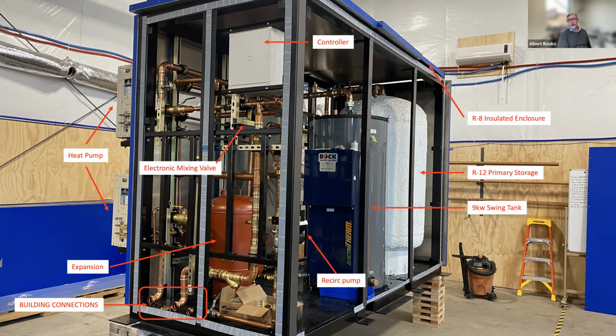The system is able to be valved off and washed and push fluid through it. Strain reliefs exist, so they can be opened up and inspected. Your mesh strainers. Not really a lot. The weakest link in the system so far in any of these systems is probably going to be the electric resistance heat pump. It's not running like a regular commercial water heater. It is a commercial water heater, right?